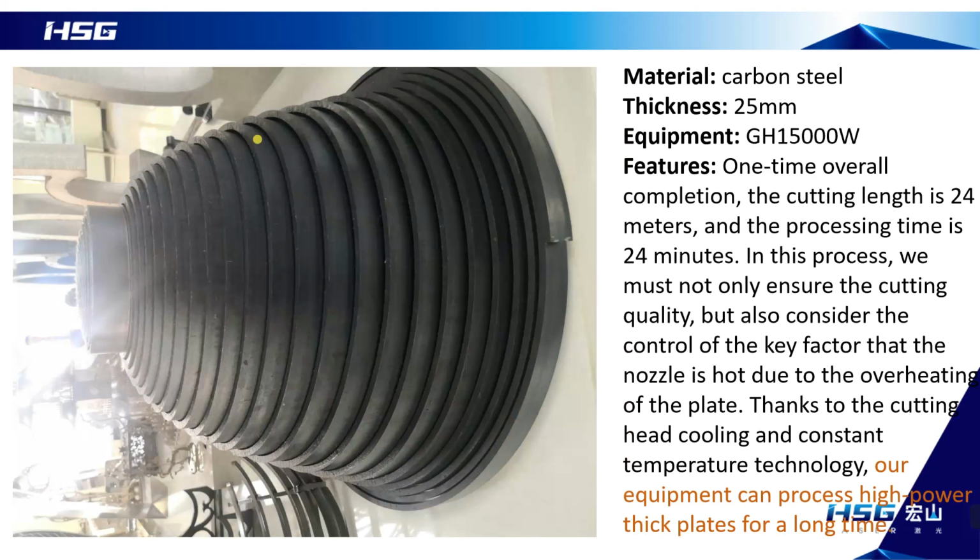This is a 25mm carbon steel plate cut into a spring. It is also cut by a 15,000 watt equipment. It shows one-time complete cutting. The total length is 24 meters. Processing speed is 1 meter per minute. Therefore, the processing time is 24 minutes.